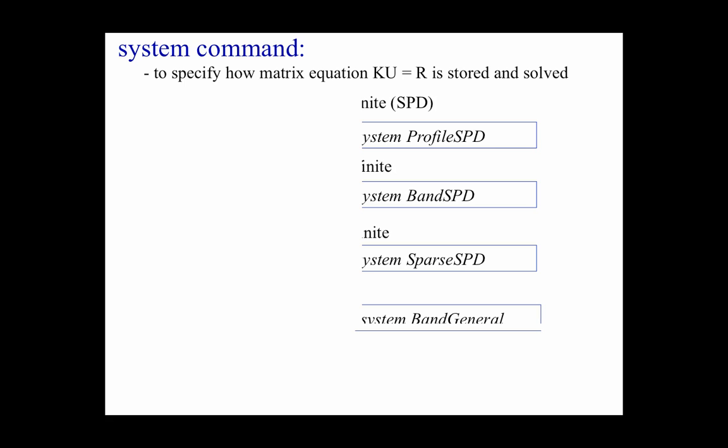Now when we go to really, really large systems, okay, I'm going to take everybody's name who's here today just to make sure I don't get this coming back from you. When you go to a really, really large system, the only type of solver you should ever use are these sparse solvers down at the bottom. There is another one which Pedro Aldrino will probably talk about tomorrow called MUMPS, which is not in the sequential version of OpenSees. But it's another option, and he highly recommends it, and it will be in the sequential version shortly.